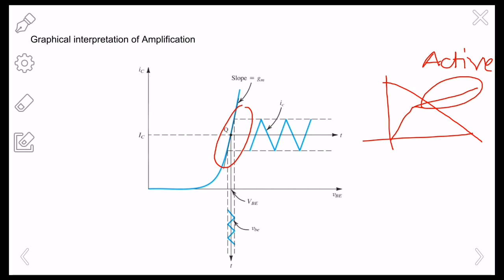You know that by now, if you have seen the MOSFET videos. You take a Q point, and you take this Q point by shifting your DC biasing at the base. After you're satisfied with a certain value, like right here in the middle, then you put the small AC signal, that small VBE. You can easily see the small VBE right here, and then this gets amplified, because see the curve right here.